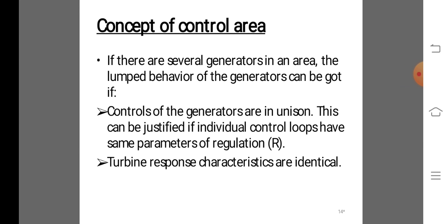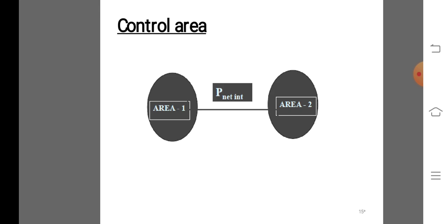If two generating stations are connected by a tie line and there is a load increment on station B, the kinetic energy of the generator reduces to absorb the same. Next, the generation increases in both stations A and B, and the frequency will be less than normal at the end of the governor response period. The load increment will be supplied partially by A and B. The tie line power flow will change as well.